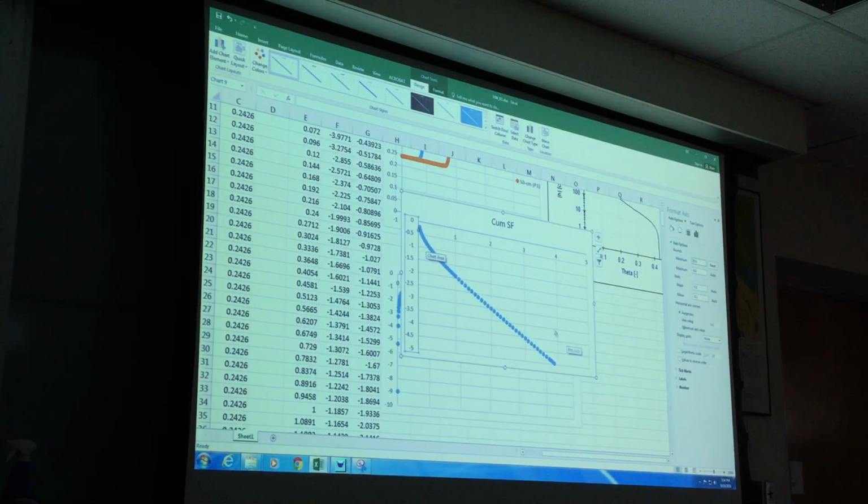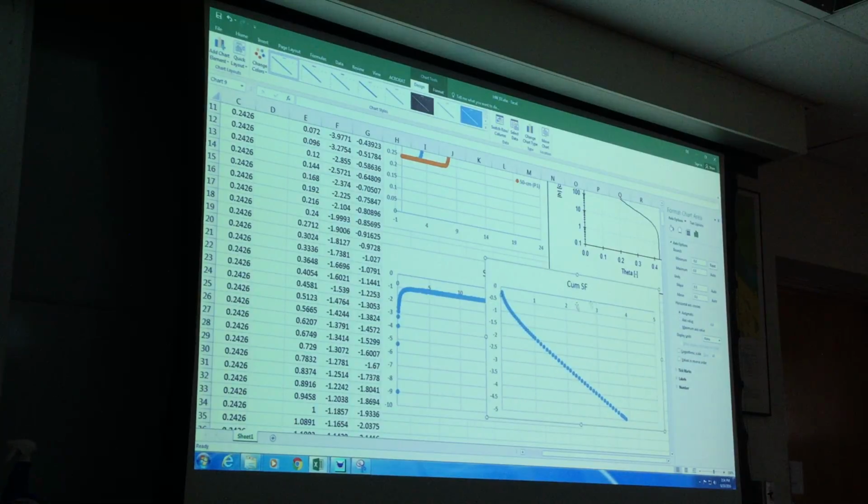This is exactly what is also shown in this one. You see higher actual surface flux in the beginning, and then it reaches a constant value. This is once the soil is saturated, and it cannot exceed the saturated hydraulic conductivity. It then infiltrates exactly at the rate of the saturated hydraulic conductivity.